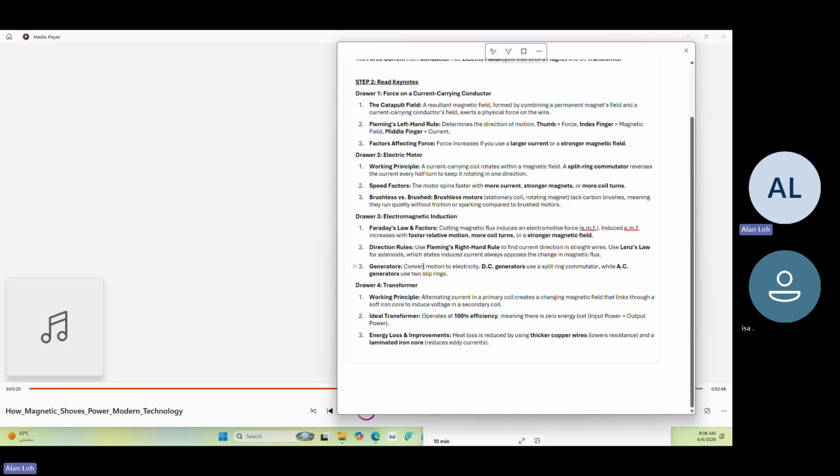Let's go back to that massive drop tower ride. The magnetic braking. Yes. Permanent magnets attached to the falling seats drop past stationary copper strips on the tower. The falling magnets induce a massive current in the copper. And because of Lenz's law, that new current creates its own magnetic field that violently opposes the falling magnets. Exactly. It safely decelerates the seats without a single moving mechanical brake pad touching.